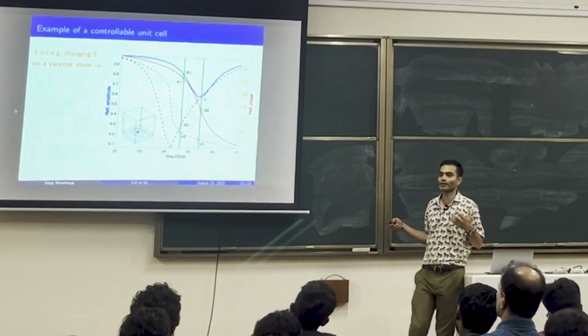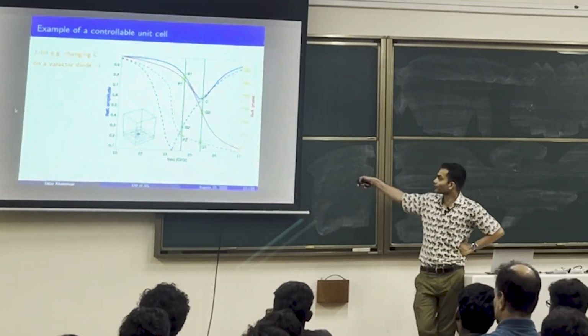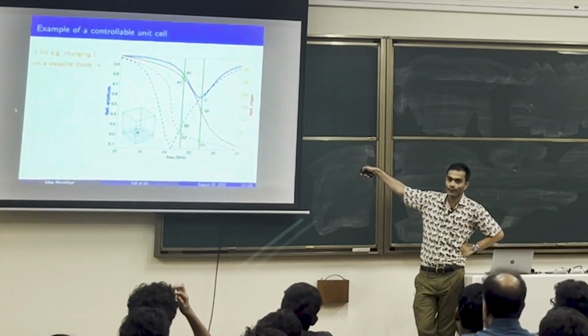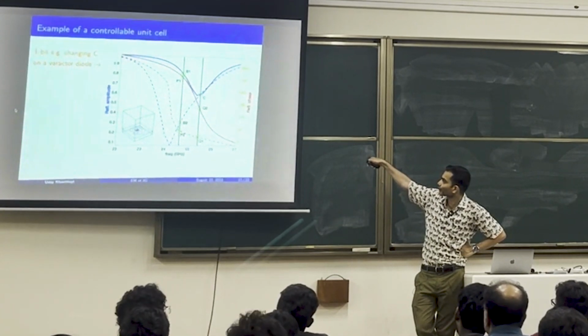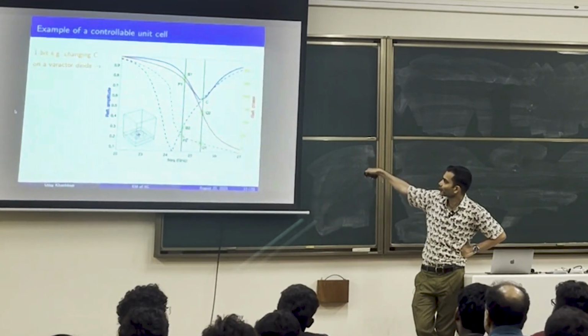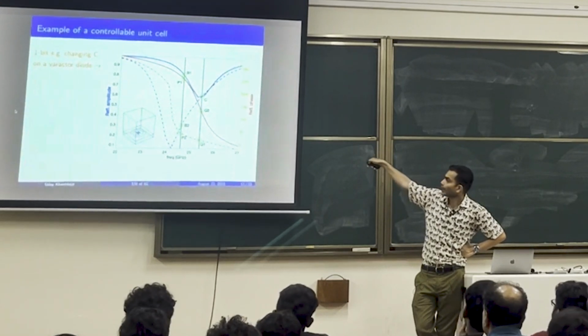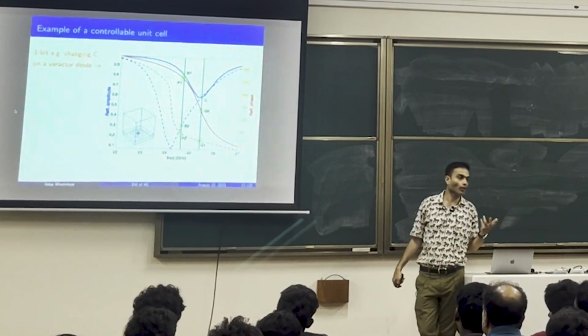The actual mystery is resolved not in the amplitude, but look at the phase. If you look at the phase, the red lines, the phase response is different. So if I pick a particular frequency, let us say I pick this black line over here, phase is P1, phase is P2. There is a phase difference between these two. And I can make this phase difference to be, let us say, 180 degrees or whatever I want.